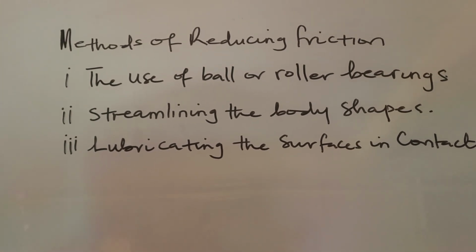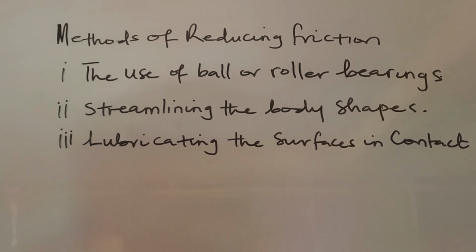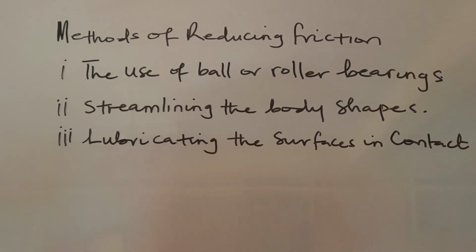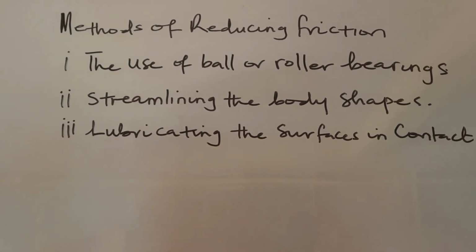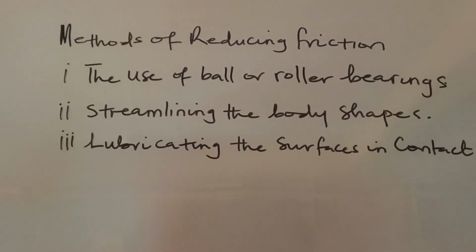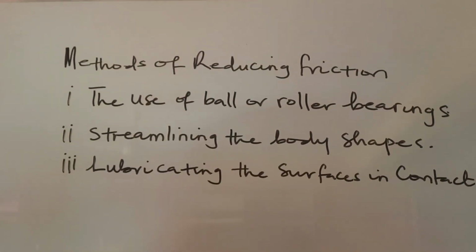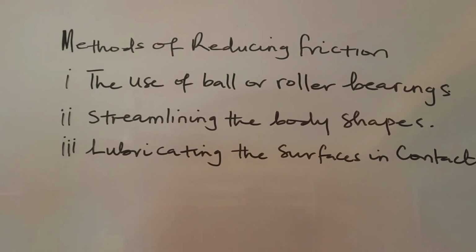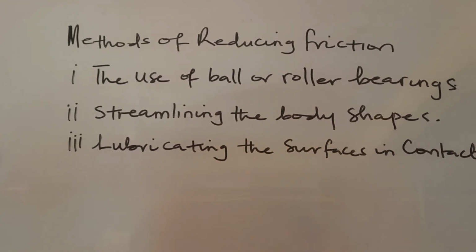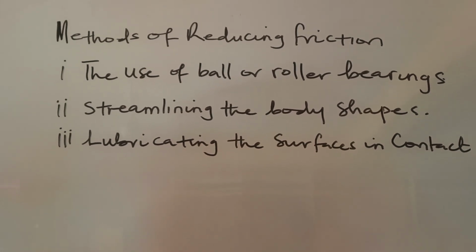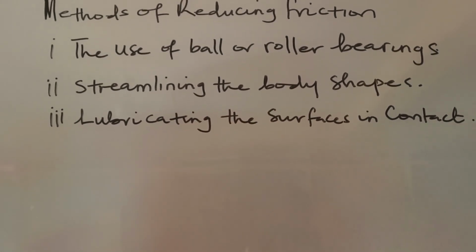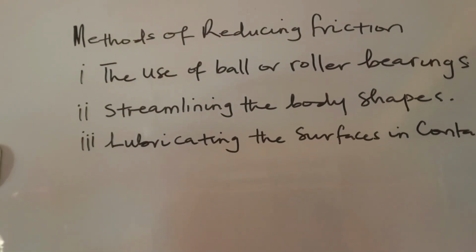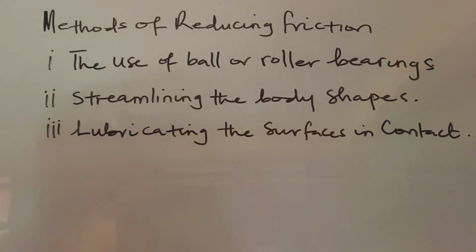Consequently, when the surfaces slide upon one another, the force of friction will be due only to shearing of this film of oil and not due to actual contact between surfaces. The thin film of oil is less than 1/1000 of an inch thick. This action greatly reduces friction and is often exploited in the lubrication of shafts turning in bearings, and in all parts of machines where relative sliding will otherwise give rise to excessive heat.